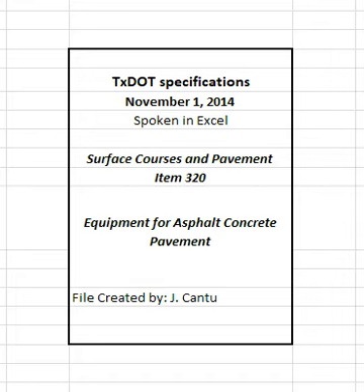2.1.1.7 Mixture storage and discharge. Provide a surge storage system to minimize interruptions during operations unless otherwise approved. Furnish a gob hopper or other device to minimize segregation in the bin. Provide an automated system that weighs the mixture upon discharge and produces a ticket showing date, project identification number, plant identification, mix identification, vehicle identification, total weight of the load, tare weight of the vehicle, weight of mixture in each load, and load number or sequential ticket number for the day.